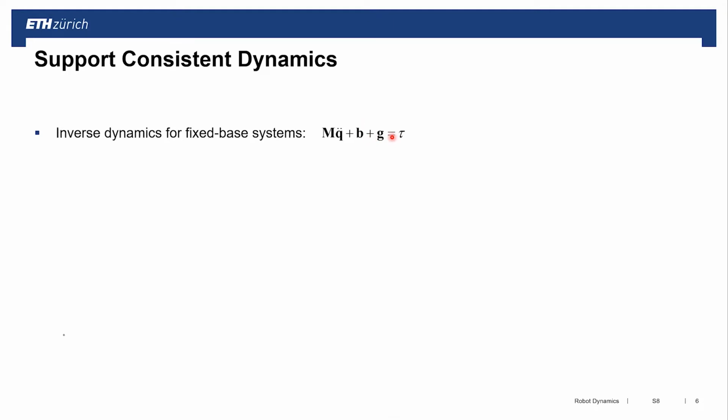And if we formulated these model descriptions of how the dynamics is evolving based on actuator input into a control law, it just changed the order kind of. We got a pre-planned desired acceleration, which is typically a function of multiple objectives that we have in how the system should be moving. We insert this in here. We have the modeled M, B, and G. So if you look at the way we wrote it in some of the notes, we had here an M hat. This was the estimate of M, and this gave us a desired torque.